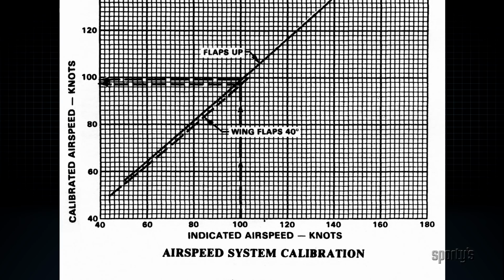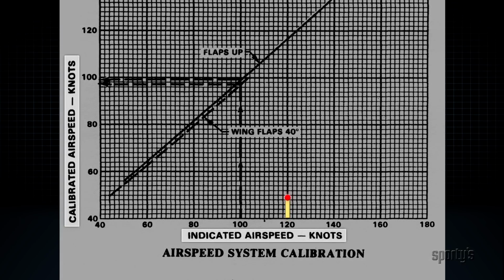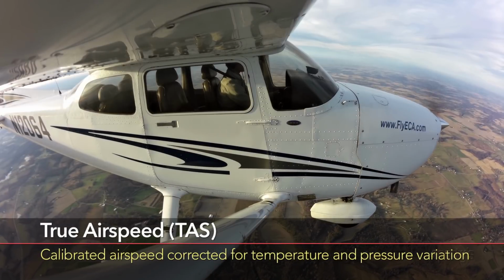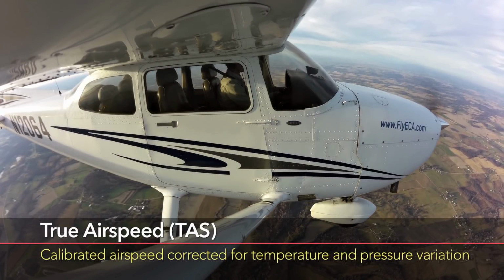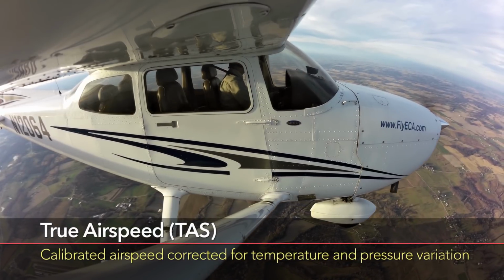To use this calibration graph, enter, for example, the indicated airspeed of 120 knots. Then go up to the flaps up line and across to the calibrated scale and read a calibrated airspeed of 117 knots. The third type of airspeed is true airspeed, which corrects calibrated airspeed for variations in air density.